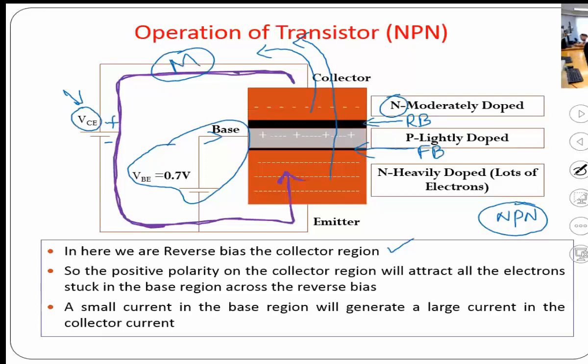Which source are you talking about? There are two sources here. Which one are you referring to? You're referring to the VBE side of it? Yeah, if you put like 1 volt right here, you're still more than 0.7, you're still good. You see what I'm saying?